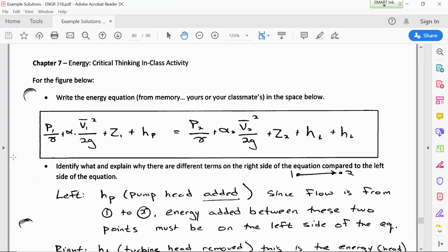All right, so the three terms of Bernoulli's equation: pressure head term, velocity head term, and elevation term, with some slight differences. Remember that in the case of the energy equation, we're adding the kinetic energy correction factor, alpha, because if we use the average velocity, we're going to be underrepresenting how much energy is tied up as velocity head. And so the other difference is that V bar means average velocity. Those three terms are the places where the energy exists at location 1 and location 2.